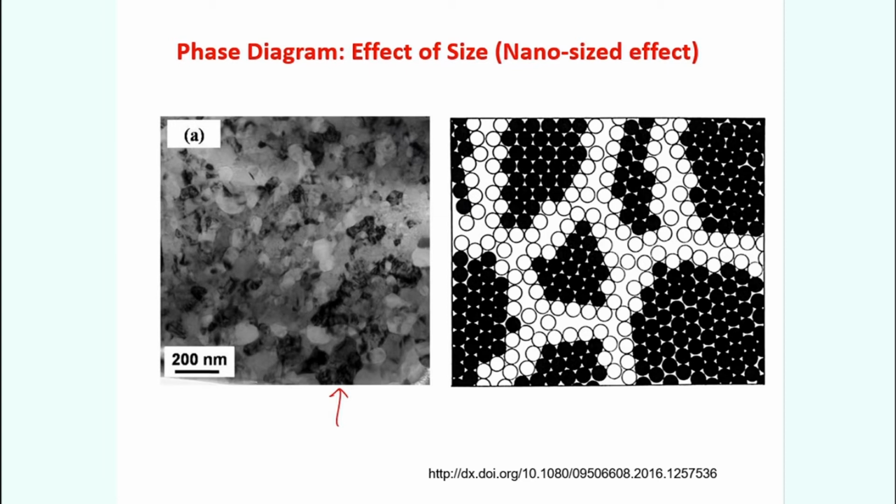So, this will lead to extra energy. These boundaries are called interface boundaries. Okay, so they are not surfaces, but actually interfaces, and these interfaces will have high energy. In a nanocrystalline size of grain, this boundary area is pretty large, and as you know, the total energy of the system is gamma multiplied by A. So gamma is one aspect, area is another aspect.